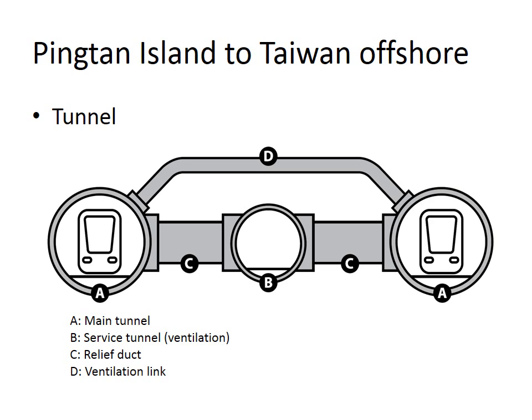We propose the additional surface tunnel in the middle because for a tunnel which has more than 100 kilometers, a surface tunnel is a must for the ventilation purpose. And in addition, when we construct the tunnel, there will be 2 TBM machines on both of the sides, which will drive simultaneously to save the time and advance the construction program.